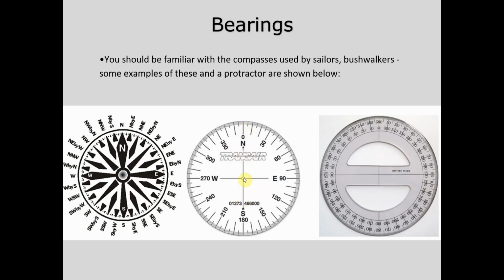We're moving clockwise, or we're rotating clockwise. So again, if I draw any line here, what we are measuring is clockwise. If this is our starting point always, I do not measure the other way around. Okay, we don't do that. That's incorrect. Always the measurement is clockwise. Number 3, the unit, as we agreed, is degrees, usually 2 decimal digits, and then minutes, again 2 decimal digits, and then seconds. We usually refer to minutes like that and seconds like that.